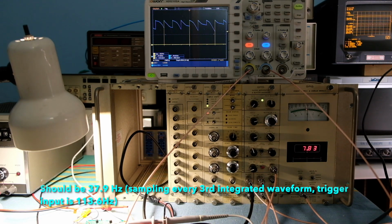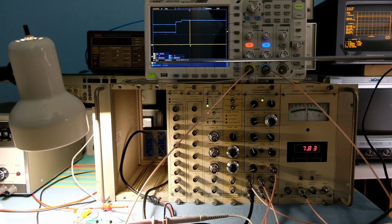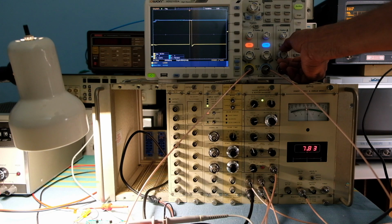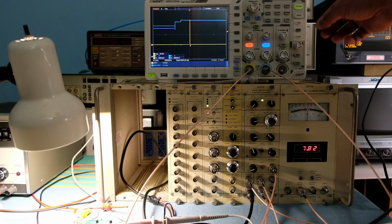So let's zoom in over here and show you where exactly I'm sampling. It's just past the reset. The reset edge is right here, and the width of the reset is a little over a division, which at 20 microseconds per division is about 25 microseconds of reset time, fairly short. But the sampling window itself for this boxcar is even narrower. It's about a microsecond or so, 1.5 maybe. Yeah, it's about 2 microseconds in this case, so it's still very narrow. Now the voltage here is 7.82. If I move the sampling point